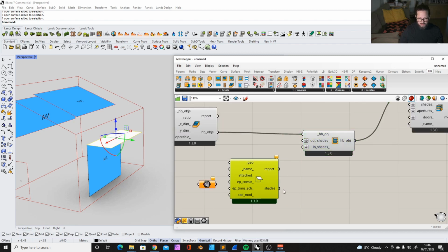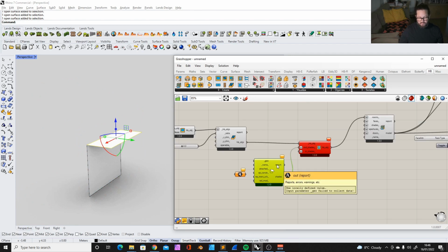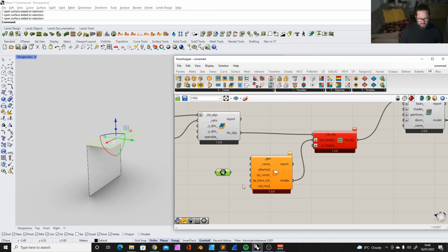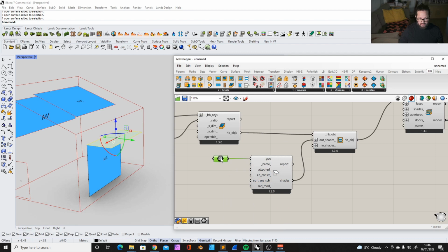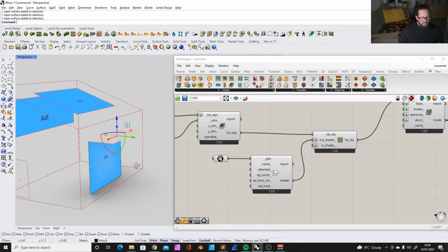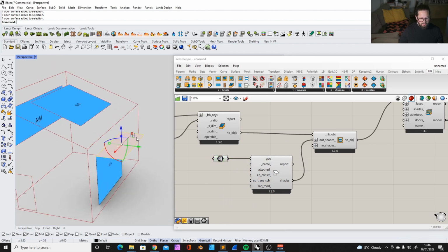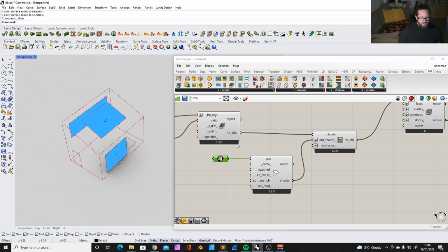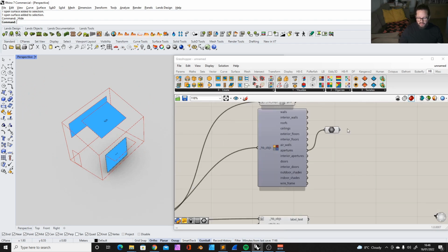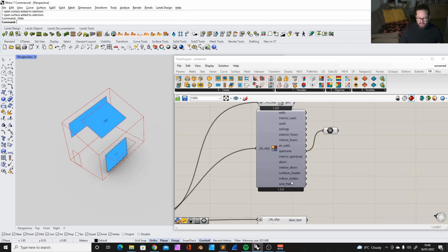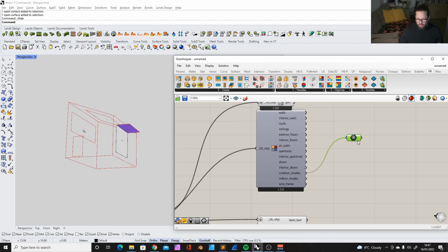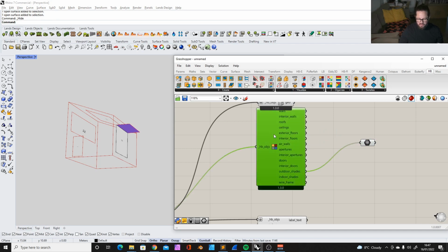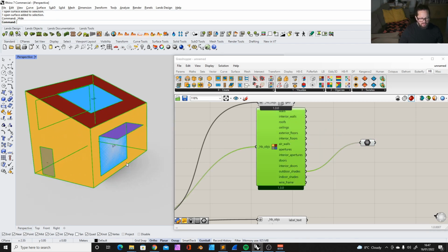So you can add custom shades. We need to define the surface and we need to add it. So now this has become a shade object. You can also hide that again. This is my shade object and I'm gonna hide it here. But it's already visible in the wireframe. And now I could go here and check if we have outdoor shades. Yes, we have a model. You can look at it. You can also always make everything visible by right clicking here on the symbol and it will color everything.